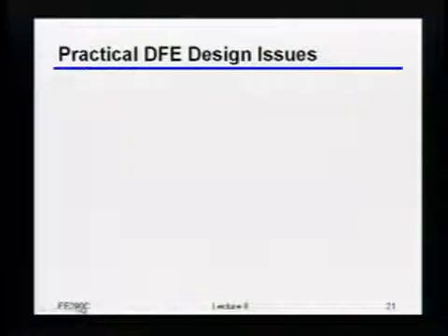Okay? So sometimes even when you do that, of course, you're still going to want to do a DFE. So you just need to keep track of when you start doing these interleaving things. That's going to interact with how you end up building the DFE. The key thing to keep in mind is that, generally speaking, the settling constraint on the DFE doesn't really change. So if you start doing interleaving, at some point you may actually be just spending more power without really saving yourself anything in the comparator itself.